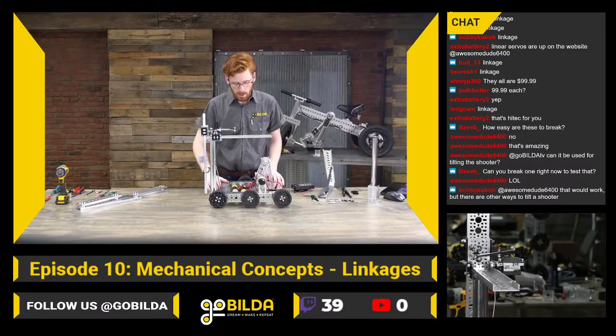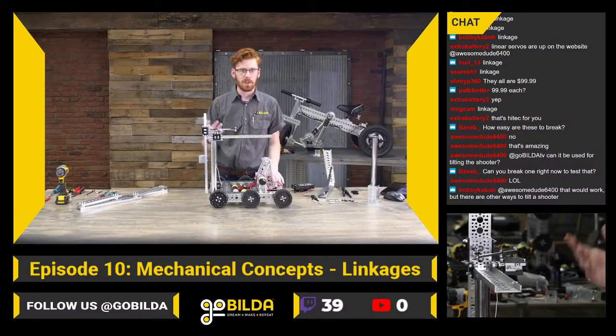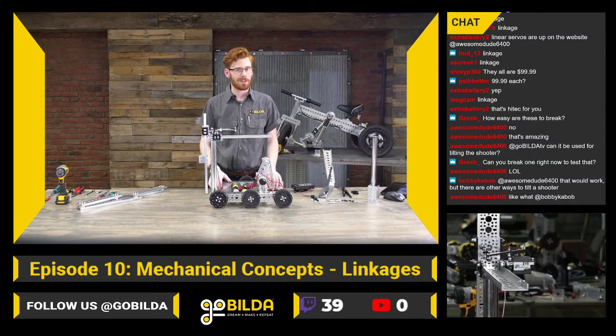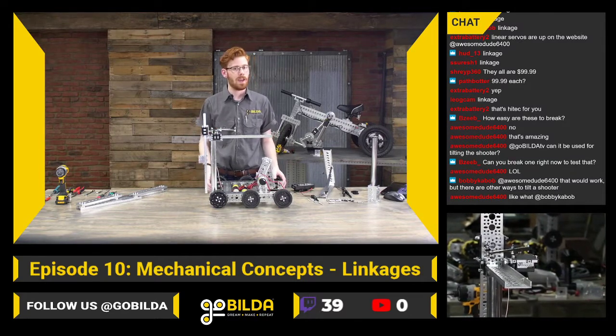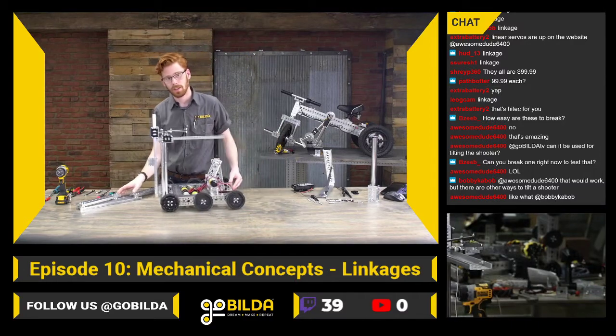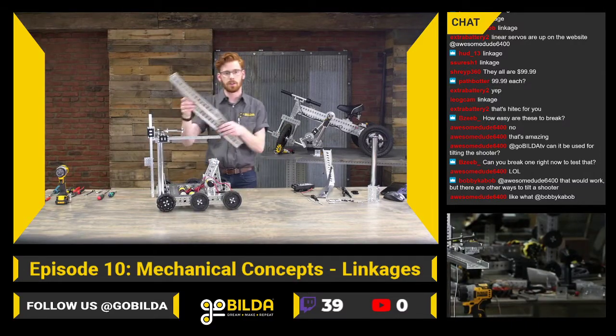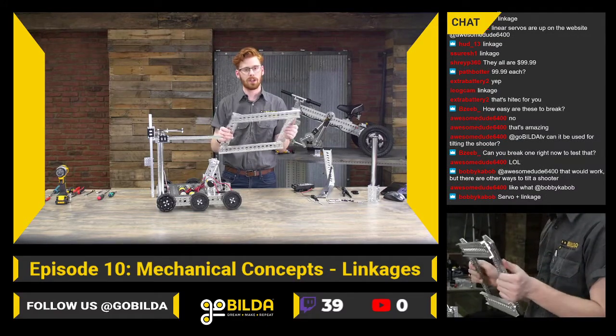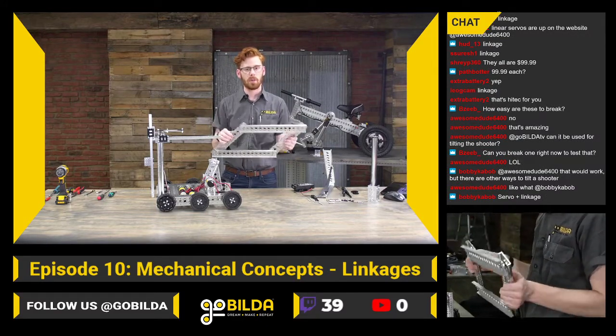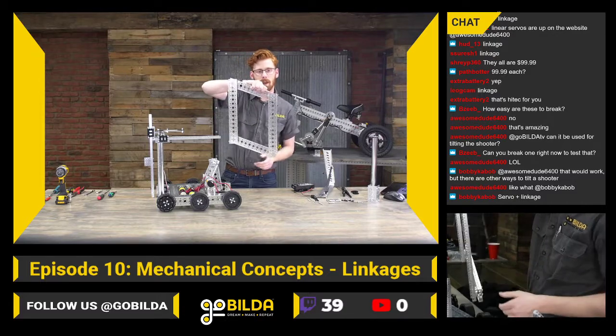So, the basis of a linkage is that it's a few different mechanical bars that are all linked together and perform some task. A linkage that a lot of you guys in FTC I'm sure will recognize is the traditional classic 4-bar. This is a great example. It's made with some low side channel and dual pattern pillow blocks, and it can be really smooth.